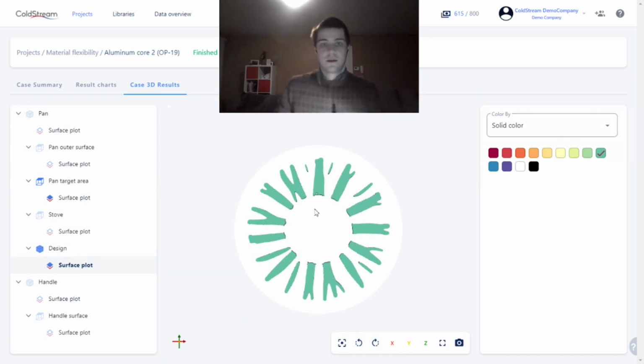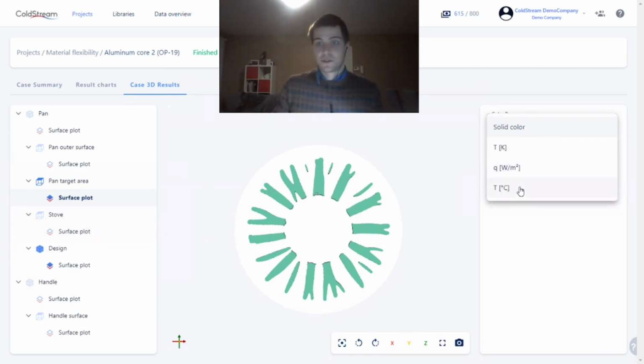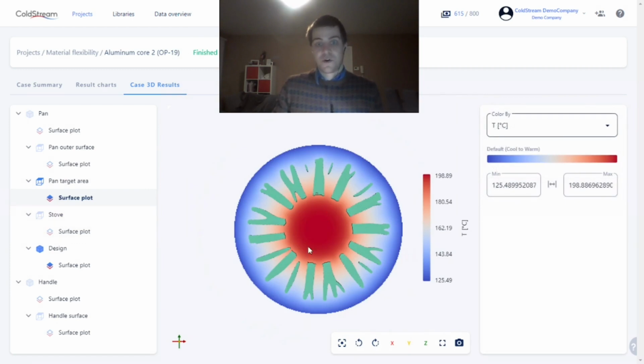Yes. So what we can see here for the aluminum core, the branches are much narrower, and with our volume constraint, that means that the branches can go further or can have a longer radial direction, which makes sense, of course, because again, our hot core doesn't need any cooling, and so it really tries to pull away that heat to the outside.